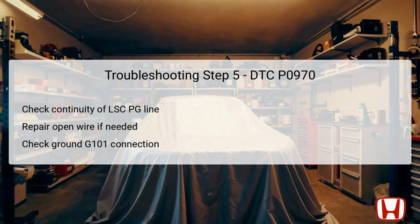Moving on to the fifth troubleshooting step, the focus shifts to checking the continuity of the LSC PG line. As with previous steps, it is important that the AT clutch pressure control solenoid valve C2P connector is still disconnected and the vehicle remains in the off/lock mode. During this test, you will check for continuity between the AT clutch pressure control solenoid valve C2P connector terminal number 1 and body ground. A positive result here means that the LSC PG wire is functioning correctly.